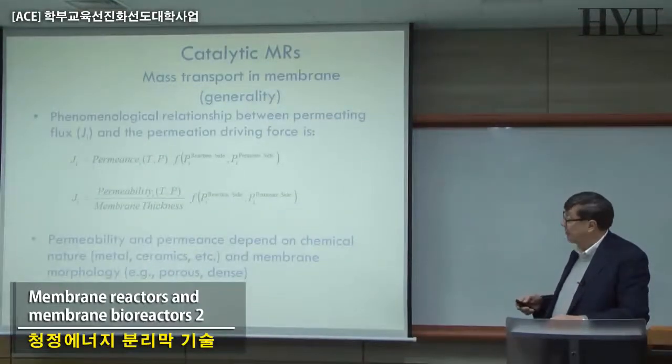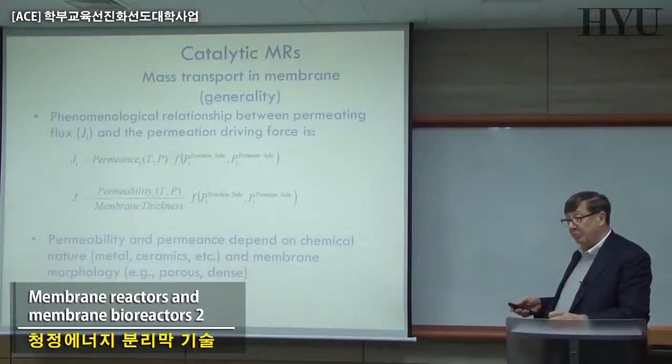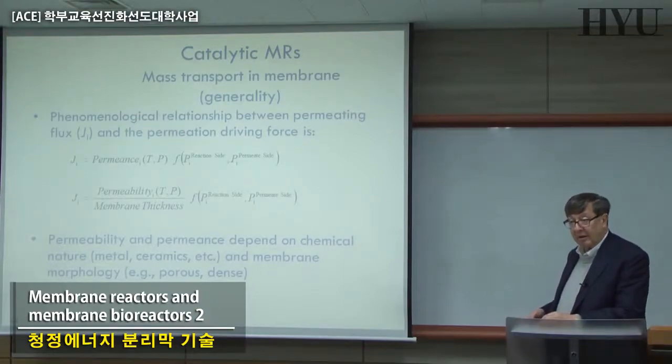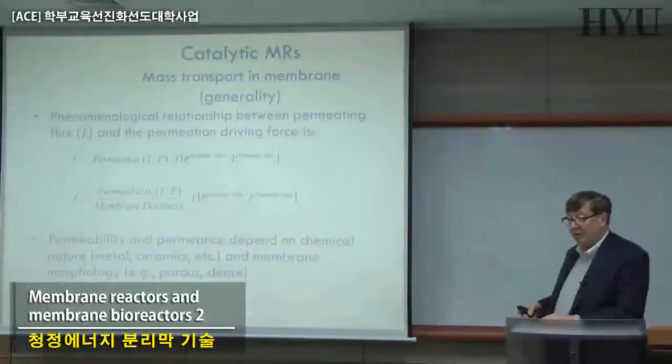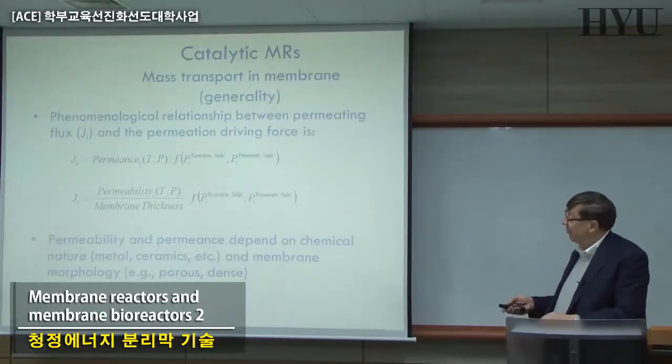And we saw last time that we can have membranes in which the catalyst is just entrapped in the membrane itself, or systems in which the membrane operation is combined with traditional chemical reactors. In one case it is an external reactor, in external membrane reactors, the other case just an intrinsic catalytic membrane system.